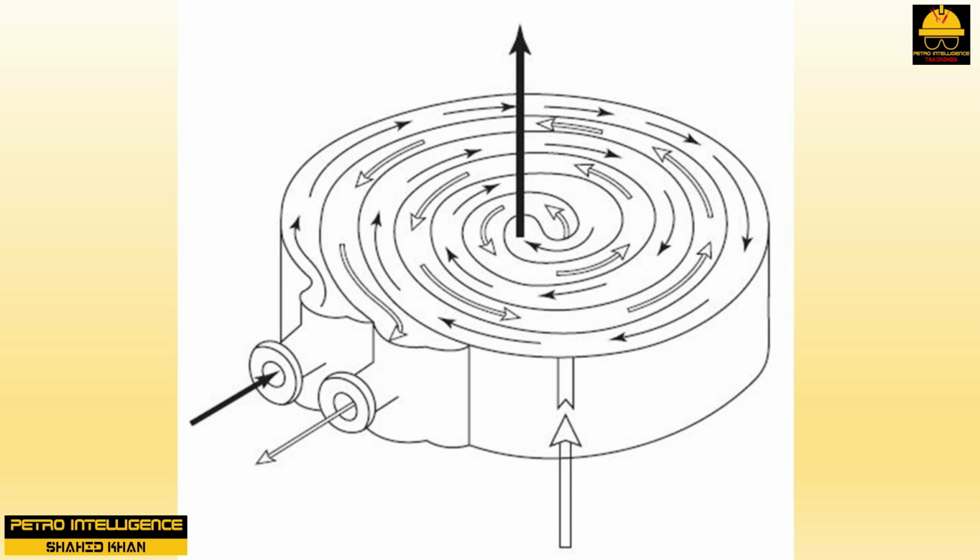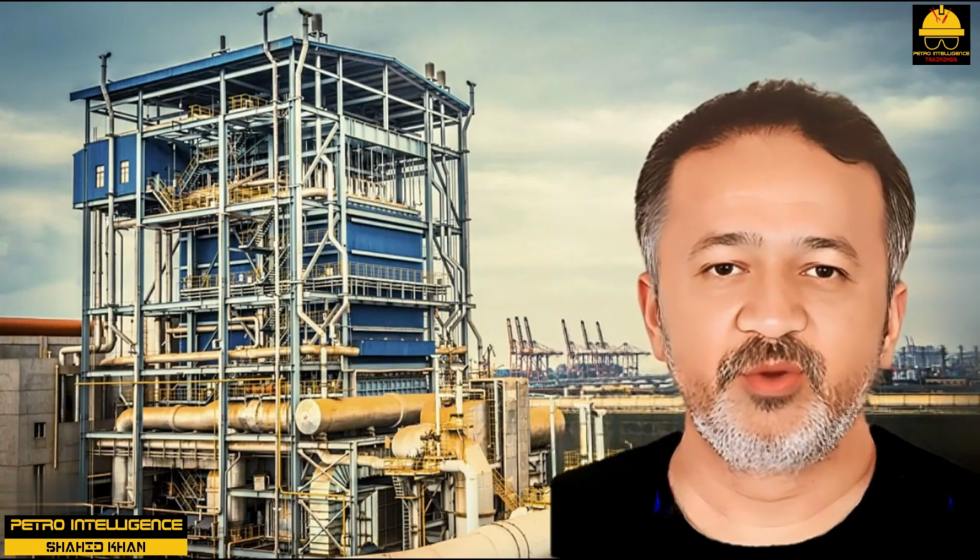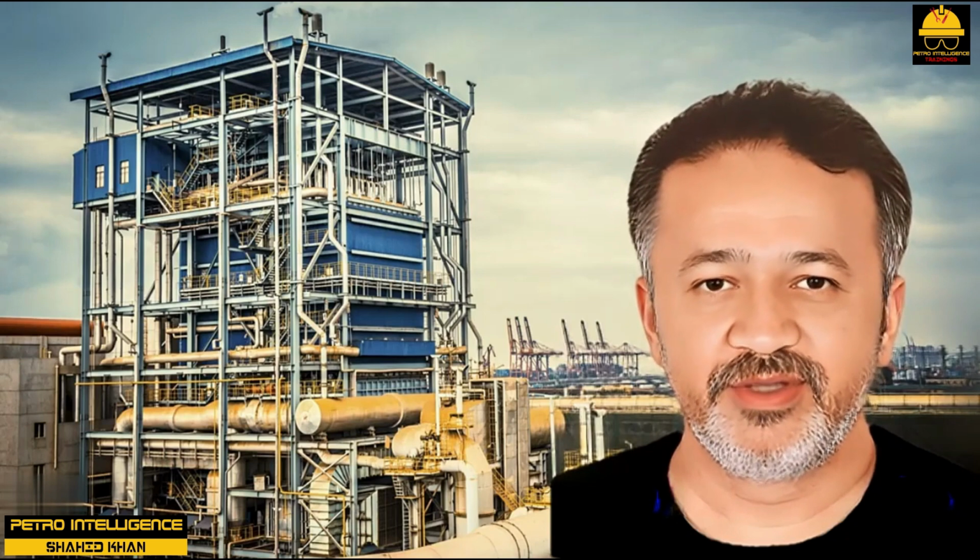Spiral heat exchangers have been used with success in refinery fluid catalytic cracking (FCC) unit service to cool the main fractionator bottoms product, where they have proved to be less subject to fouling than other types of exchangers, although one client commented that they had needed to make awkward repair welds between internal channels.